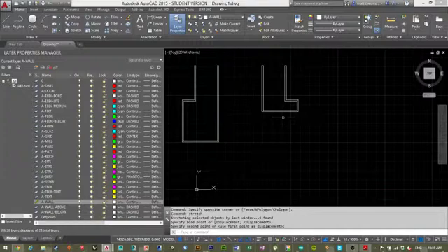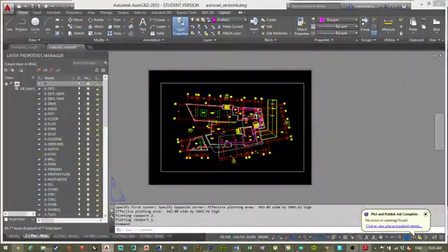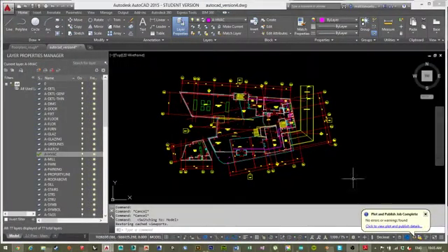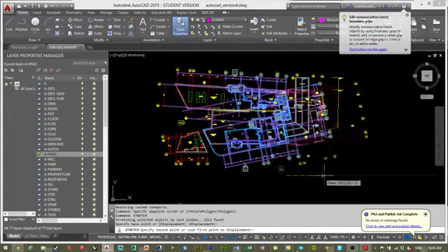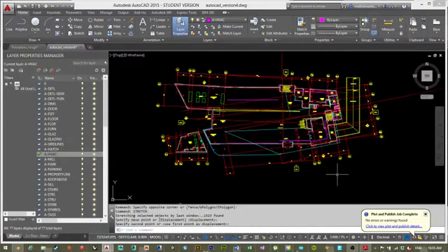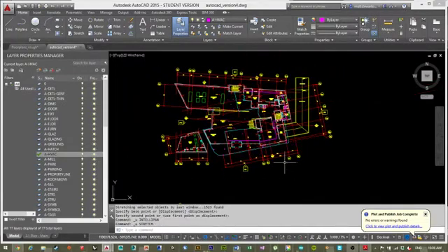So moving whole walls and whole parts, if your whole building just needed to shrink, get a foot thinner, and if it was extremely complex, you can just select half. Obviously this won't make that much sense, but stretch, right? I'm just taking everything I selected and stretching it out. I'll go over dimensions briefly, but the dimensions are tied to two points, your start and your end. If you change the distance in between, like stretch or scale, the dimensions will change automatically.